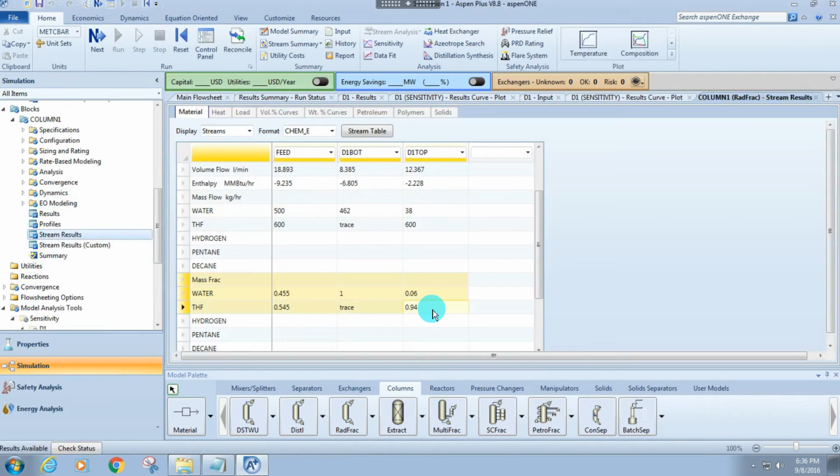So you'll see that, well, I don't want to get too much into this, but increasing this purity to more than 95% is impossible because of the existing azeotrope. And I know that I uploaded the azeotrope finder on ASPEN, but because I'm telling you that there is one, and we know that there is an azeotrope, we don't need to necessarily go into the finder, but develop a YX diagram that's much more useful for us. Do you guys remember YX diagrams from separations, McCabe-Thiele?